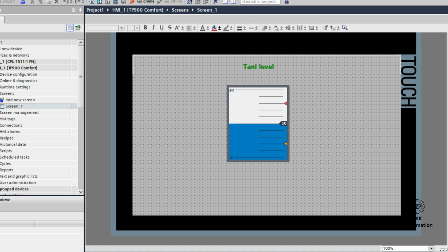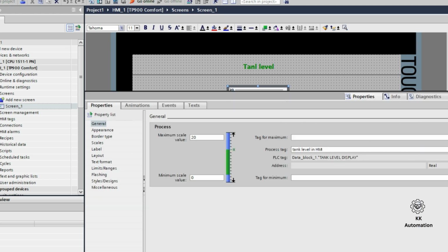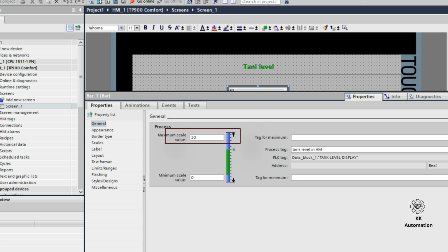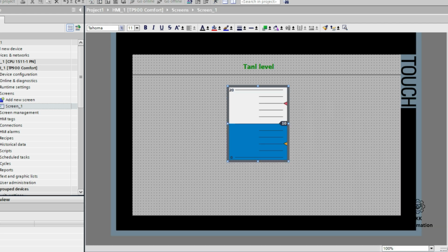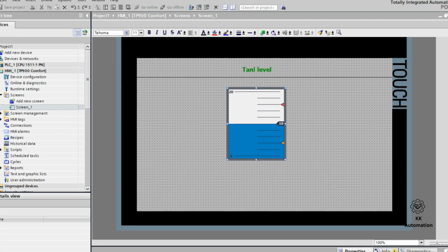We have a tank on our HMI display, and we want to show the fill level of that tank. The range we want is 0 liters at the bottom and 20 liters at the top. Everything in between is a linear scale. That is our goal, a simple clean fill level display in liters. Now let us look at how this works inside the PLC.